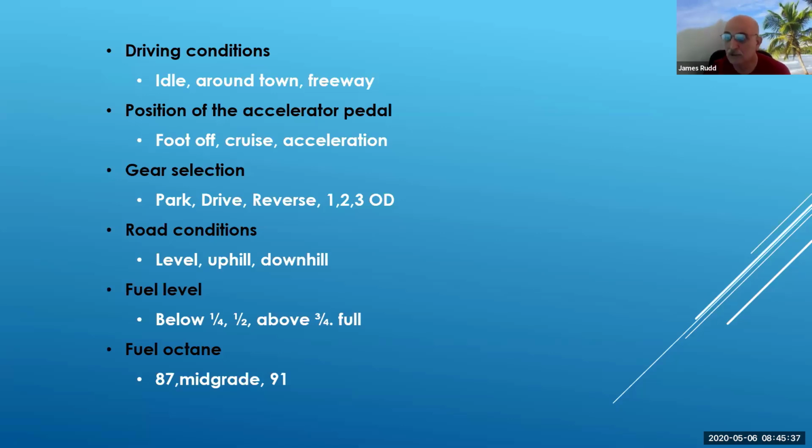And then road conditions: was it on level ground? It only does it uphill. There again, the groups all come down to a spark plug, coil pack, spark plug wires, and this is a true test of when you're going uphill. One of the things I liked about working in Torrance was I had the peninsula right over, and it had a nice hill. If I had a customer complain about a hesitation and I wanted to verify it, I'd drive it up that hill. Downhill, you may possibly have some transmission issues. And there again, as diagnostic technicians in performance.